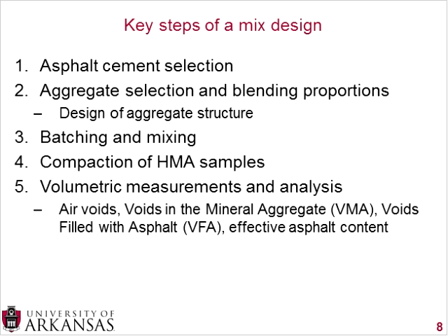Recycled asphalt pavement, or RAP, is becoming more and more popular. Now people are even putting shingles in, and that starts blurring the line between asphalt cement and aggregates. But these different additives you can also put in, which I'm not going to cover in this presentation, but especially the larger aggregates are in charge of designing the aggregate structure.